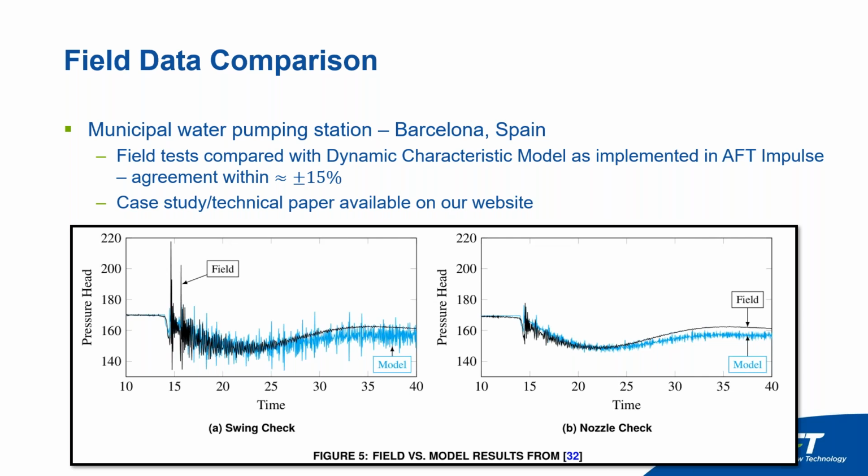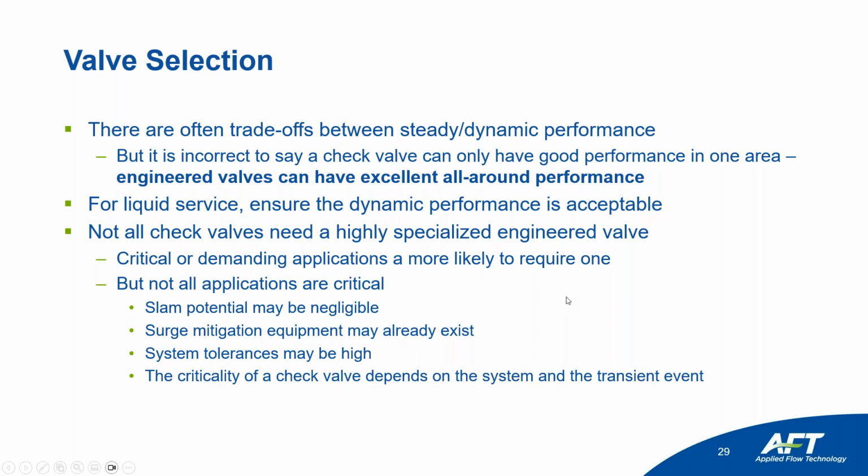You can also see in these graphs here the dramatic difference between a swing check valve and a nozzle check. One of these clearly behaves better in the sense of not causing large amounts of surge. The scale here on the two graphs is the same, so you can see a dramatically lower surge with that better check valve design. So speaking of check valve design, just very briefly, there are often trade-offs between steady and